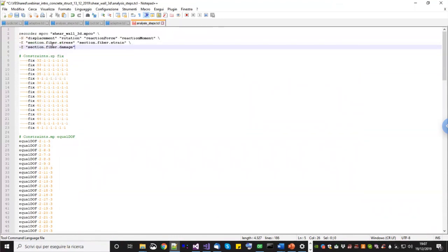And of course, inside the STKO installation folder or on our website, you have the description of the command. So basically the name, then this option that lists all the possibilities for the nodal results, element results, and so on, and you're fine. You basically will generate the output file for STKO, and you can read it in the post-processor. That's great. Thank you.